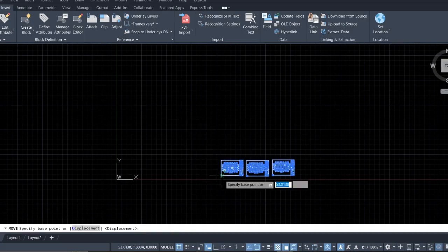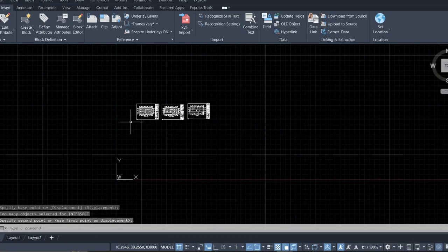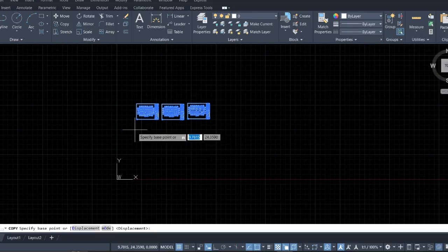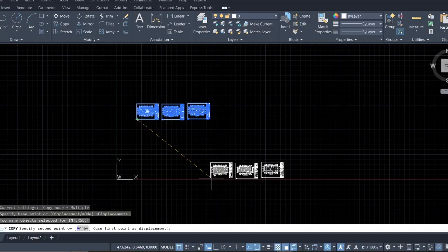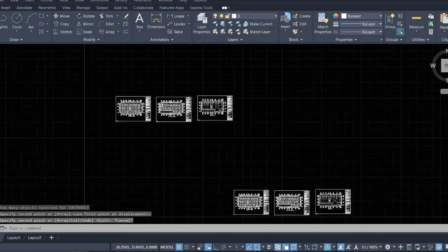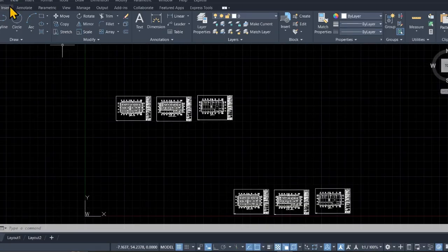Remember, if you had a DWG, you could not have imported it as a PDF. Rather, you ought to have imported this as a DWG. You will have used the open object here. If you had this PDF format file which has the architectural plan, you are doing an insert.